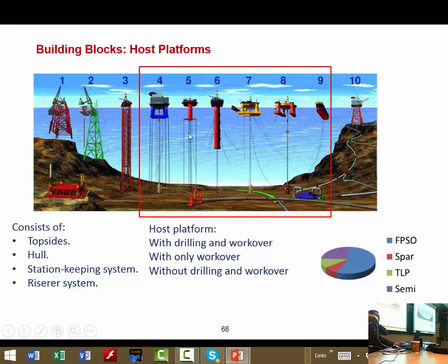Yes. Number 6, you have these spirals on the cylinder. Yes, these spirals, because you have a long cylinder, and in an area like the Gulf of Mexico, you have this loop current effect, and you have very high current, like 3-4 meters per second, which is quite high. This can make some vortices around the hull, and these vortices will make some vortex-induced motions.